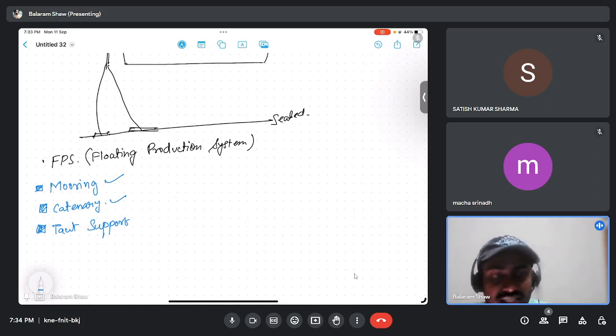It can consist of 100 millimeter diameter rope or cables, steel wires, or several materials. Mostly chains are used. These heavy chains will be attached at the anchor, with rope, chains, and other materials. So that was catenary mooring.